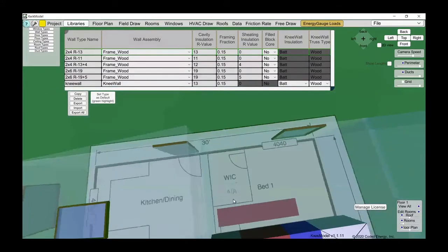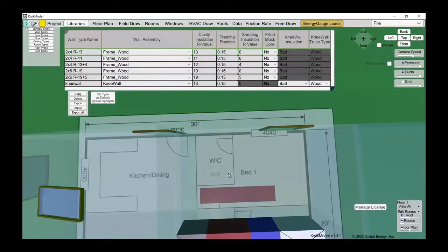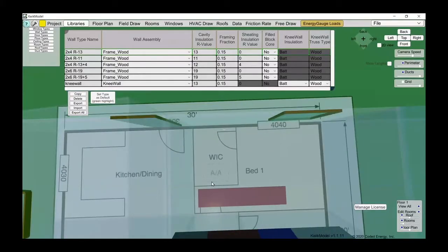That's a really interesting question. I think you're getting really kind of precise here, but if you wanted to, what you would have to do is draw a little tiny room that's the same size as that attic access, group it with the rest of the room around it, and then the ceiling for that attic access, I assume you're assuming that it's just uninsulated sheetrock, and you want to account for that.